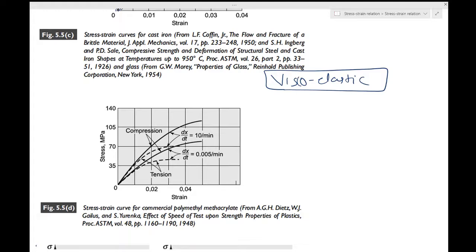So you are already aware of those ideas from your knowledge in chemistry. At higher temperature, metals can also exhibit time dependent effects. Okay, so we are not going to study that, but you should be aware that at higher temperature, metals which don't usually show a time dependent behavior are at best plastic, which is time independent. Plasticity is time independent. At very high temperatures, they can also start to show viscoelasticity, which is time dependent.